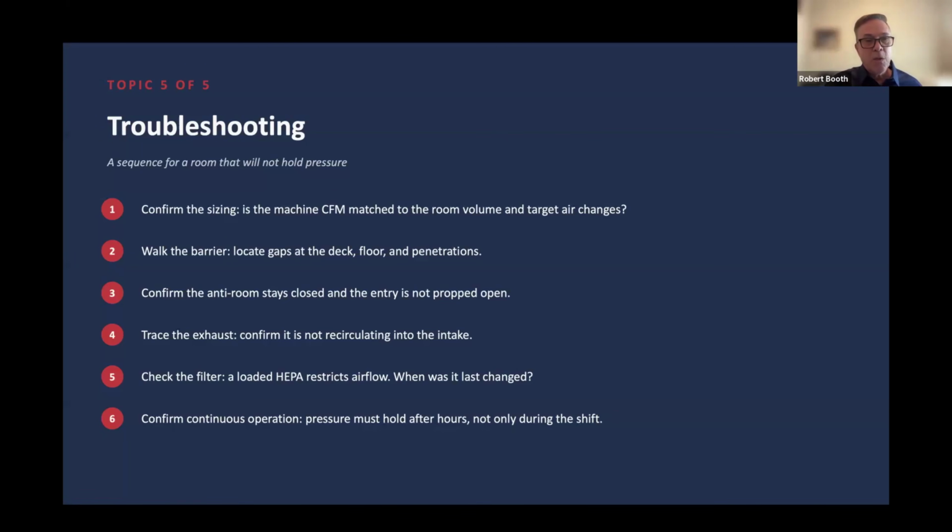So what we're trying to strive to do is when you're doing your weekly checks or your daily checks, go over and look at the machine and say, okay, guys, this is going to be out of range. You're at 1.25 inches, and at 1.5 inches, we need to change the filter out because we know by our engineering calculations, you're going to get below our static pressures, and you're going to get below what we desire for the machine.